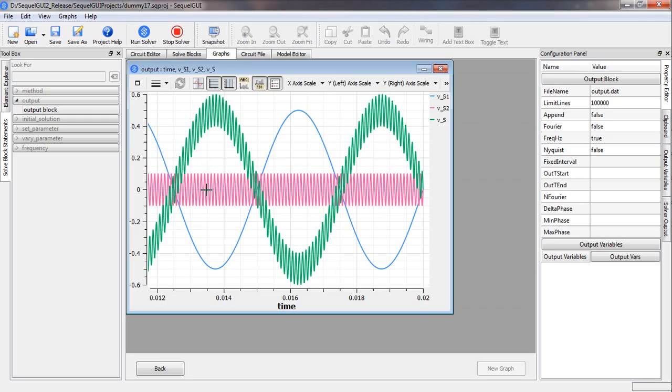This is VS2, the high frequency input voltage, and this is our VS, the output of the op-amp summer. So notice that this high frequency voltage has got superimposed on the low frequency input voltage, giving us VS. And note also that VS has got inverted because our op-amp summer is an inverting summer.